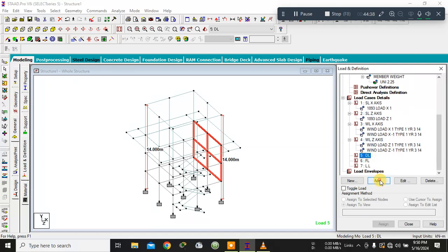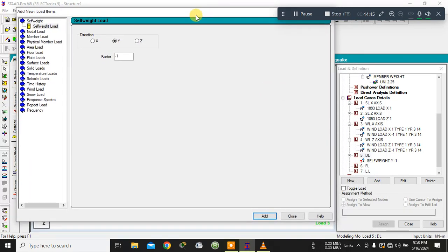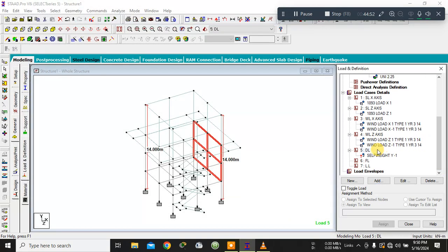Now you have to apply dead load, that is factor of safety as 1. Simply I will apply it for the self load, because I am not applying here load of the floor finish or any kind of floors, because here fluid pressure will already be present, so that one will accommodate for everything.